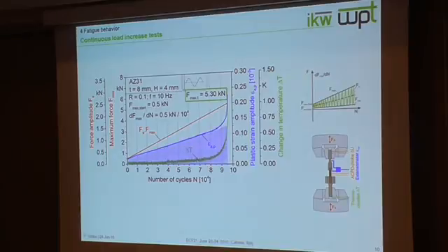And as you can see, and as I told before, there is a transition point from the linear slope to the exponential slope in both cases. And we can get an estimated fatigue limit for the specimen and for these materials. So this is shown as a very easy way to do it, but of course, in fact, we use mathematical algorithms for that to get the specific value here for the estimated fatigue limit.